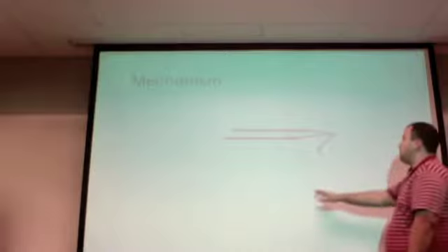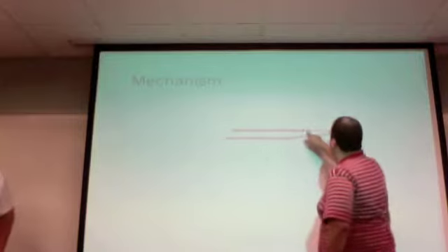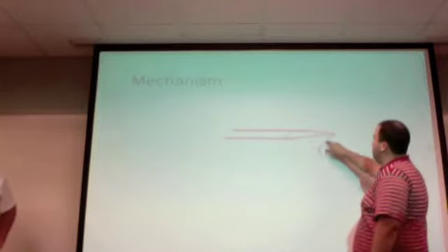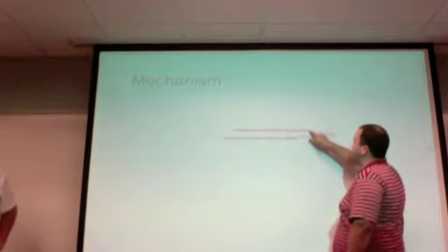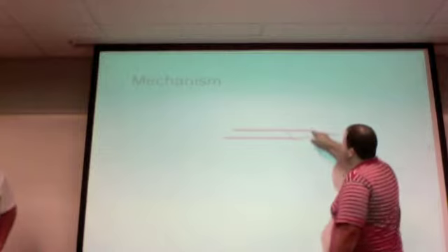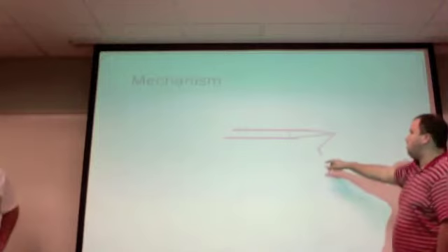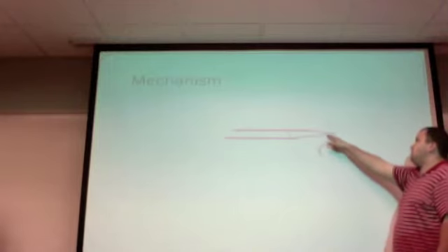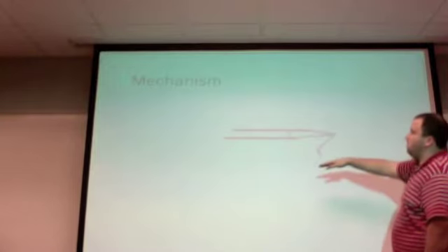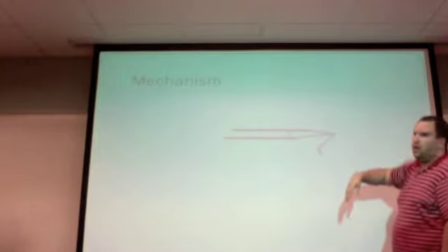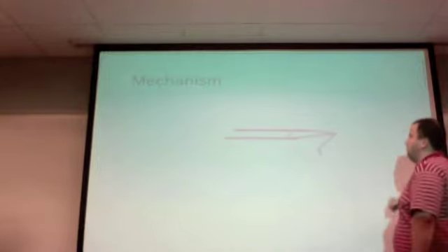All right, this is our slider crank mechanism. Here you can see the slider, R2, SL, R3, and this slider here represents R1. Since the mechanism was able to go through different lengths of R1, we needed to make R1 itself also be a slider. For this specific application, we added a blade to S and changed the angle from 5 degrees to 30 degrees in order for it to be an excavating machine that you could see in agricultural applications, where the machine will cut through the ground and make holes for new seeds.